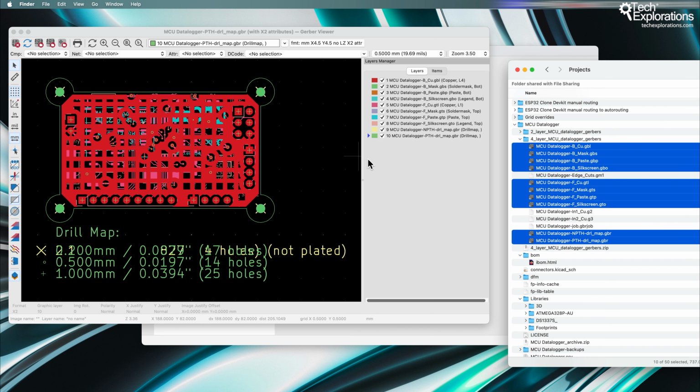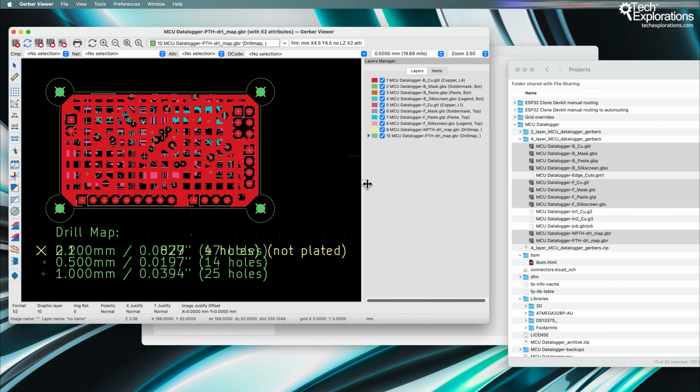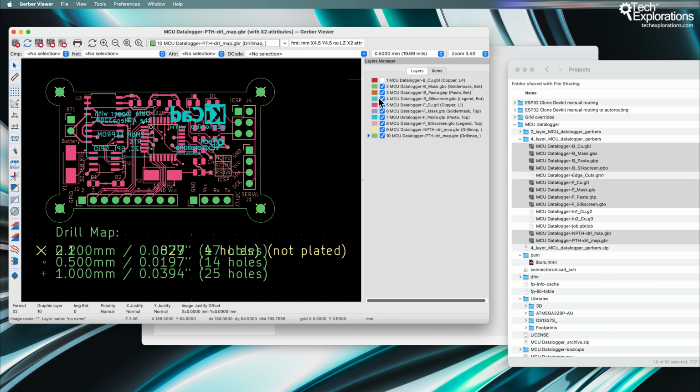And that's what it looks like in the Gerber viewer. So the Gerber viewer allows you to inspect the PCB before you upload it for manufacturing, and that allows you to detect any potential problems that you didn't pick up earlier in the process, or that the schematic and PCB editor checkers didn't detect. So the Gerber viewer is a sort of quality control tool.